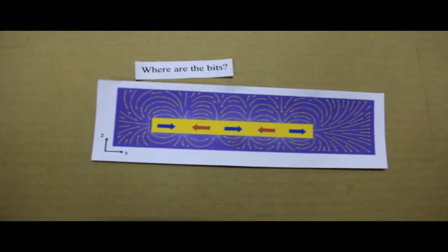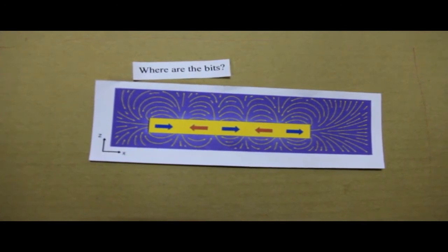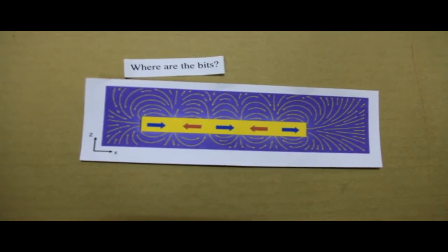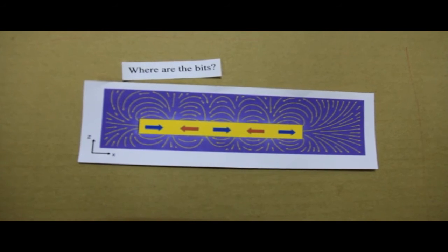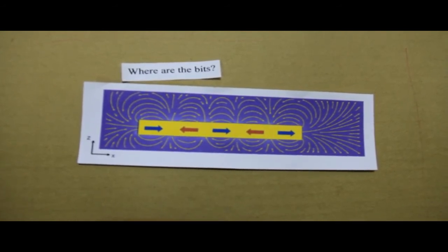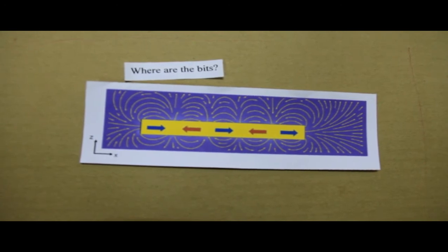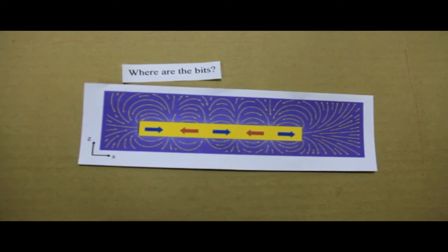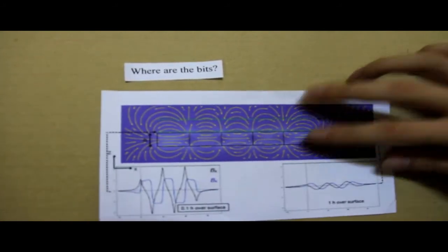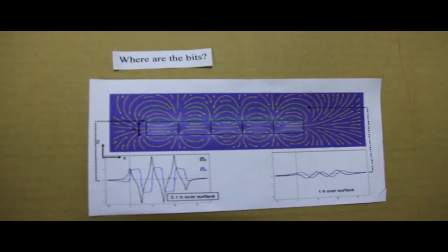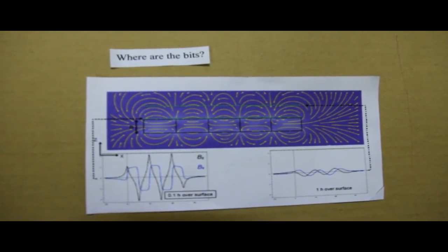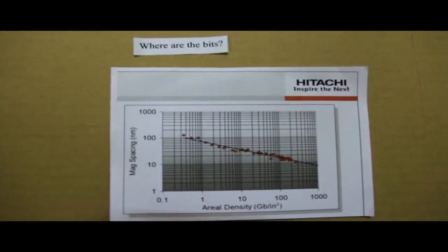The magnetic field produced by a line of magnetized bits is characterized by changes of field direction corresponding to transitions between areas of opposite magnetic moment direction. Please note that the magnetic induction lines, the B lines, are schematic and simplified. They are calculated assuming that the area of the storage medium where the bits are stored consists of parallelepipeds with magnetization exactly parallel to the x-axis, which is constant throughout the whole bit. Magnetic induction strongly decreases with the distance from the surface of the storage medium. The x component of magnetic induction changes sign in the vicinity of the transition between oppositely magnetized regions.